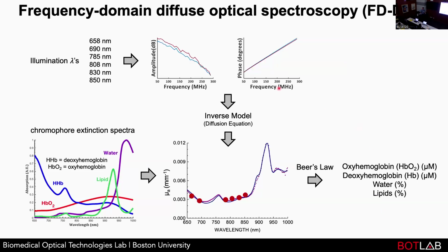Okay, so here you could take all these measurements sequentially, one at a time, and you're doing a frequency sweep. The integration time, so to speak, the measurement time for the avalanche photodiode can typically be pretty short, like maybe microseconds. And so this whole frequency sweep could take less than a second.